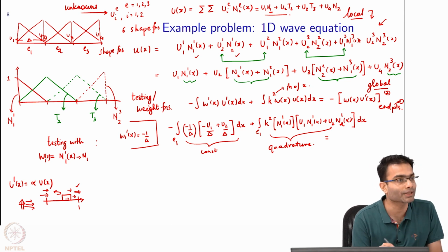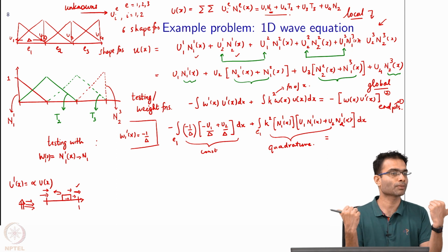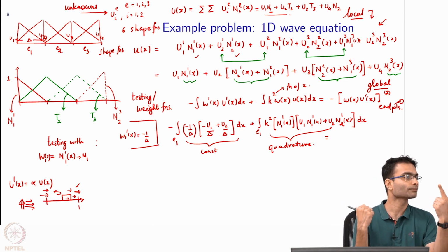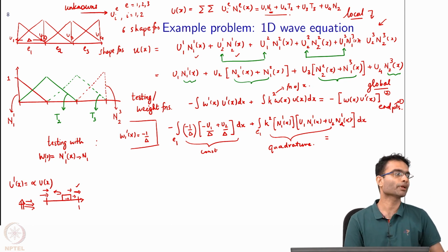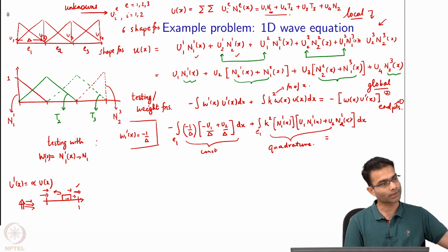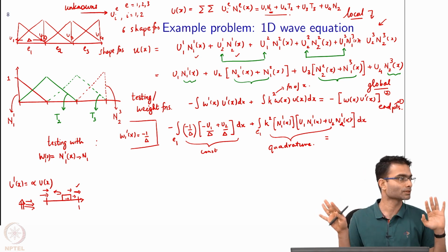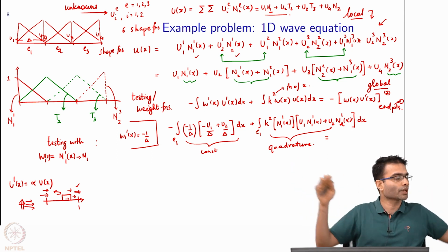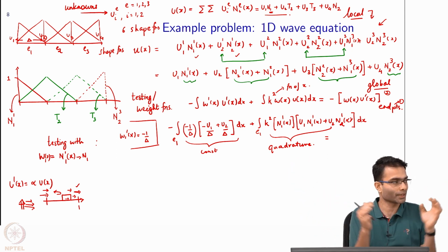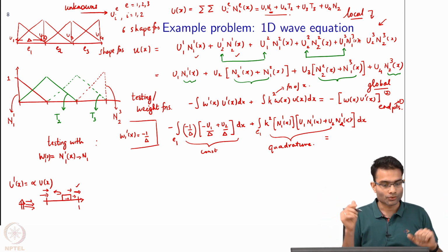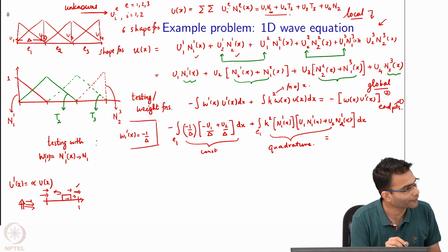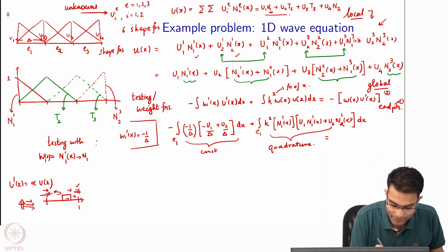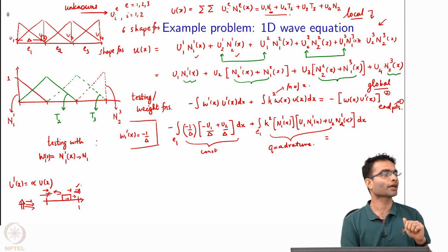So, this boundary condition that I am saying, that no reflection from the boundary should be applied to the total field or the scattered field. Scattered field should not reflect back. Supposing I delete the object, then there is no boundary condition to impose. Incident field can enter from one and exit from the other, and that is consistent. But scattered field is always going out. We are assuming that the object is fully contained inside the simulation domain. So, what is fine? Exactly, the scattered field is outgoing, right. So, here the scattered field is outgoing, here the scattered field is outgoing. So, the boundary condition should take care of scattered field, not total field.